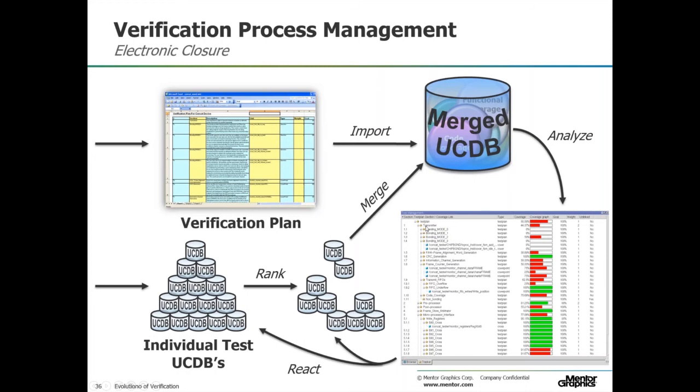And I can look and say, my transmitter right now is only 44% tested. Why is that? Let's drop it down. Well, I've done no testing on bonding mode 0 or 1. I've got 50% coverage on bonding mode 2, bonding mode 3 has 0% coverage. It's 0% because neither one of these cover directives has been activated or tested. CRC generation looks like I've completely tested all the objects within there.